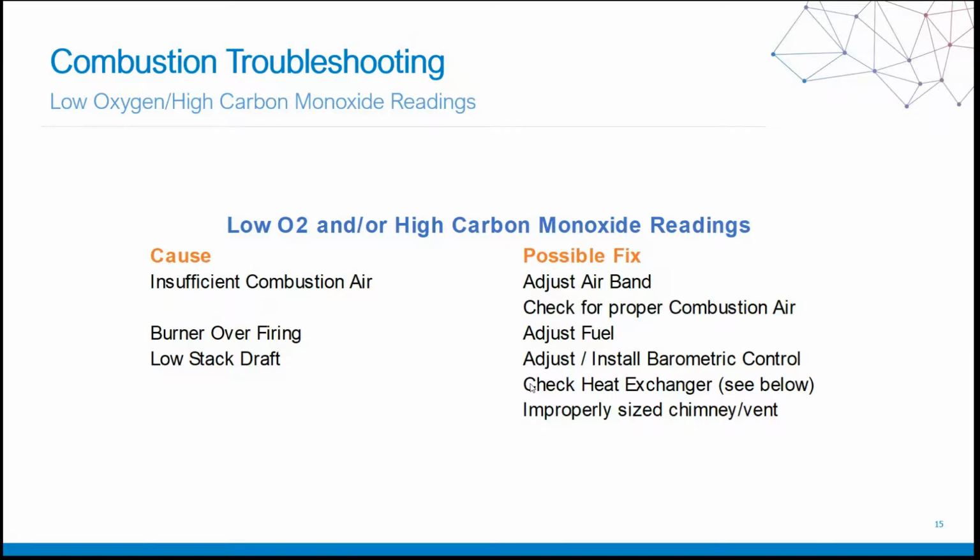First off is low oxygen or high carbon monoxide readings. Well, one of the causes of that could be insufficient combustion air. For oil systems, you could possibly need to adjust your air band. Or for a gas system, check for proper combustion air. Do you have enough air for combustion? The analyzer will tell you such.